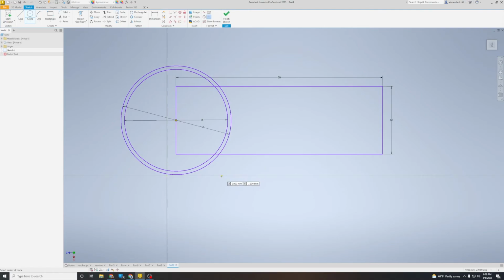This is important because this inside bit of this square and this outside bit of the square are going to move against each other. So there has to be a little bit of a gap between them. But that gap can't be so big that it's able to fall apart. I'm going to use this line tool simply to demonstrate that this inner curve is too big to fit past this outer curve, because it would be touching or passing through this line. Getting rid of that line now.